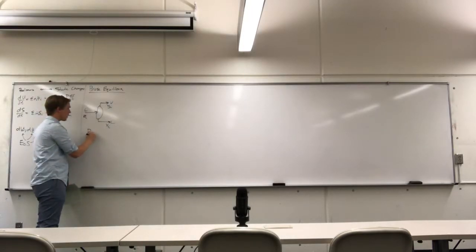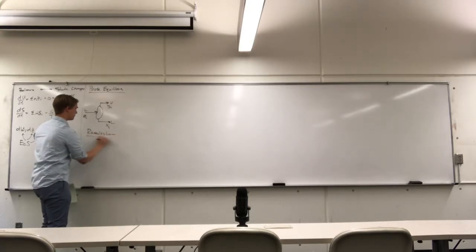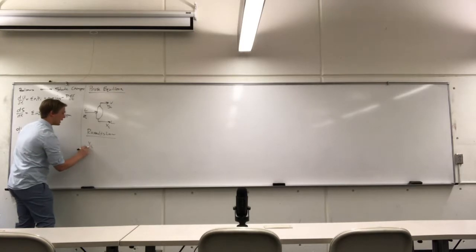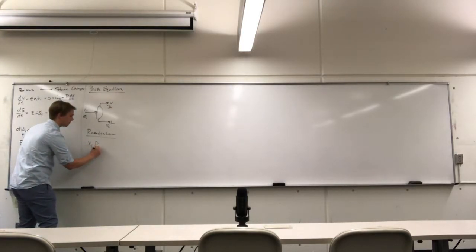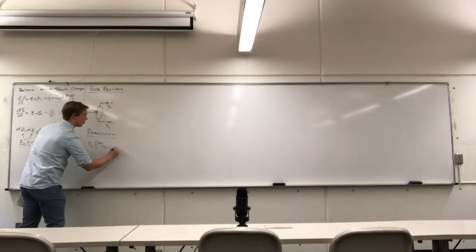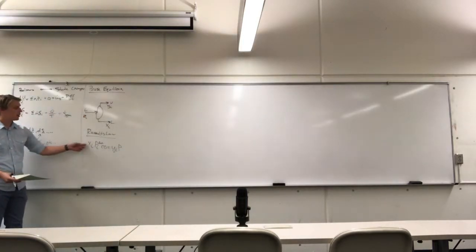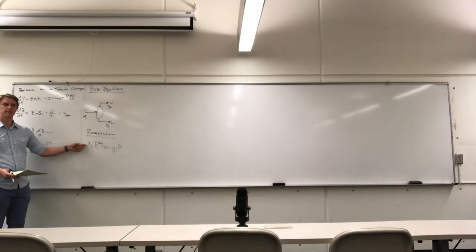And we use what we call Raoult's law, where we can relate the molar composition of the liquid, using the saturation pressure, to the molar composition of the vapor phase. And this has to be satisfied for every species in the system.